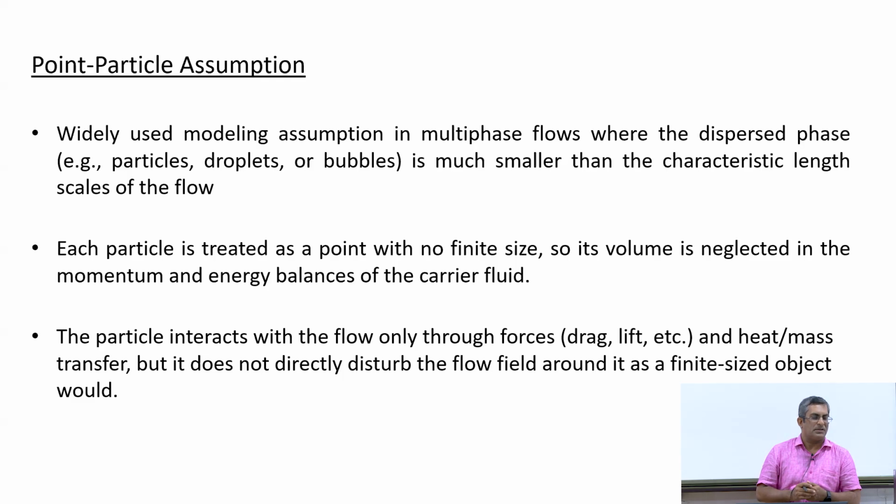So for that purpose, there is a model called point particle assumption, which is widely used in multiphase flows, especially where the dispersed phase is much smaller than the characteristic length scale of the flow. If you are considering very small particles, for example, particle flow in a channel, and the channel height is, let's say, 0.5 meter, and the particle size is, say, 1 to 100 micron.